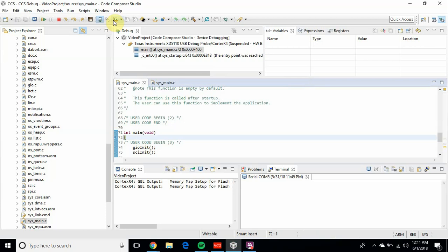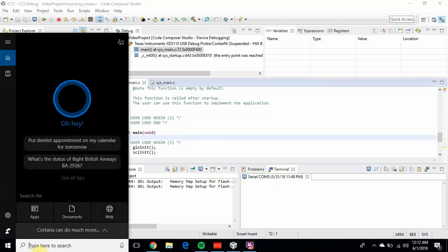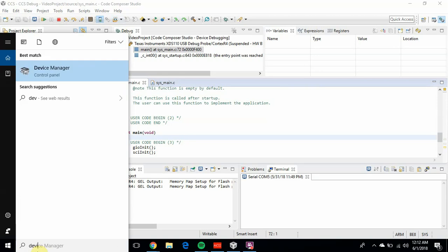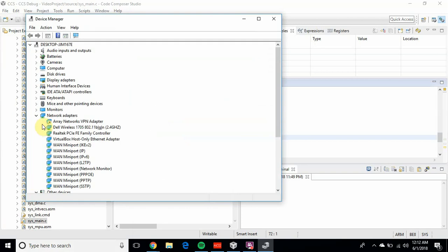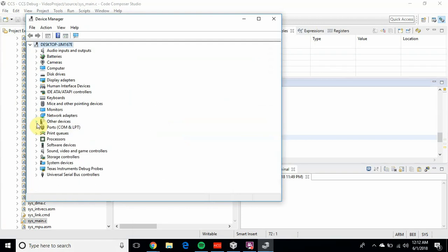So your computer has different communications ports that are used for exactly what it sounds like, internal communications, or incoming communications, I should say. So what we're going to do here, before you start running your code, is go into the Windows Device Manager. If you haven't used this before, this is essentially just a big list of all the I/O within your computer itself. And what we're going to go look at is ports right here, so COM ports. So this is the entry point of the connection between your dev board and your computer.